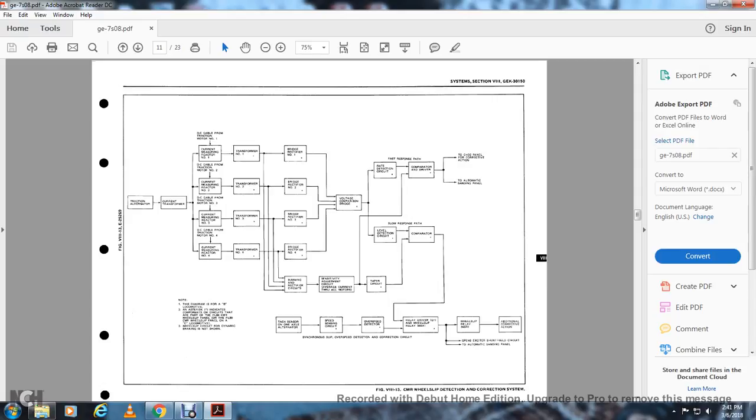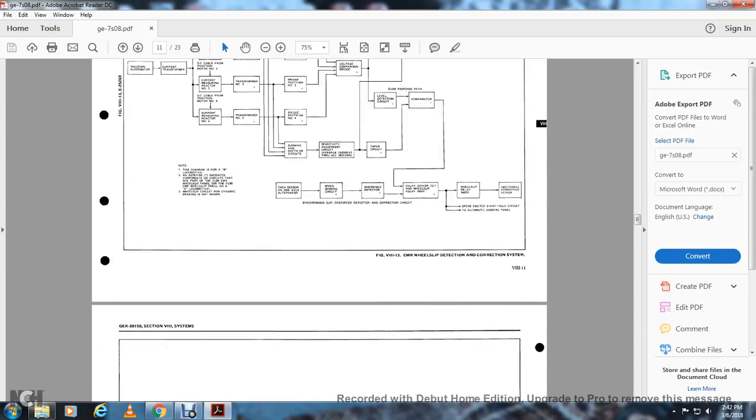Also, your bridge rectifiers go to a voltage comparison bridge through the rate detection circuit, which goes to the comparator and driver, level detection circuit comparator, and the comparator circuit goes to the relay drive and wheel slip relay, which is started by the tach sensor on one axle alternator, speed sensing circuit, overspeed detector, relay driver, and wheel slip relay. And then that goes to the open exciter shunt field circuit, automatic sanding power, wheel slip relay, and additional corrective action.